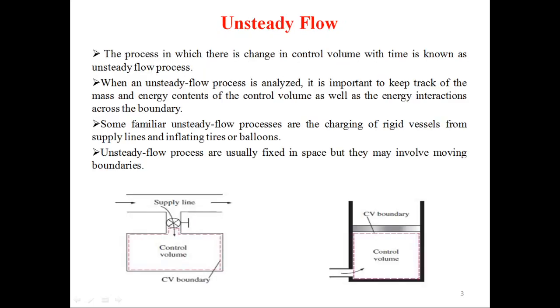Unsteady flow: the process in which there is change in control volume with time is known as an unsteady flow process. When an unsteady flow process is analyzed, it is important to keep track of the mass and energy contents of the control volume as well as the energy interactions across the boundary.